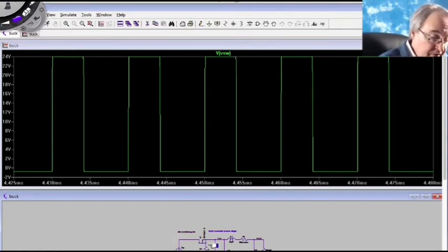When the MOSFET is on for the DTs period, the switch node is equal to VG, and we have 24 volts for VG. When the transistor is off, the diode comes on, and the switch node voltage is essentially equal to ground, so we have 0 volts, or a low voltage.